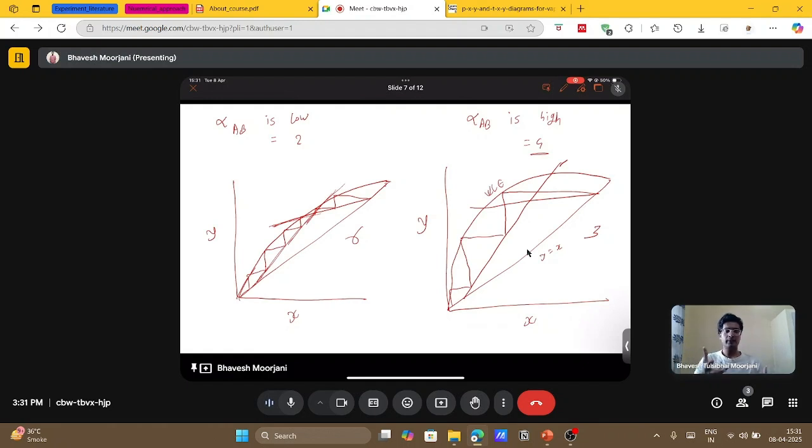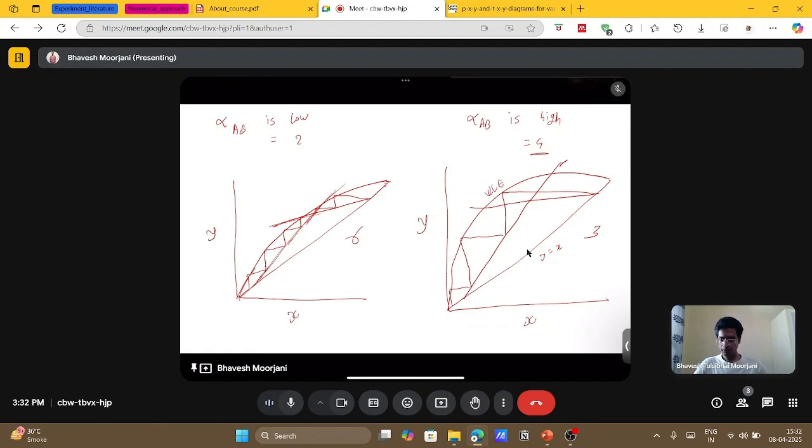One is obviously the experimental approach, where you do experiments at every temperature and pressure condition. Let's say we want to generate a TXY diagram at different pressures. So you do experiments at various pressures, compute this plot, and then decide how much separation is possible between our two components at various pressures. Okay, so that is one approach, and another is a theoretical approach where we use a theoretical model to compute the VLE data. So here we will look at both approaches.